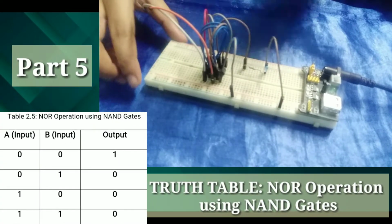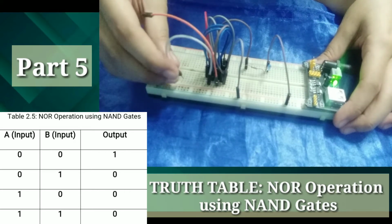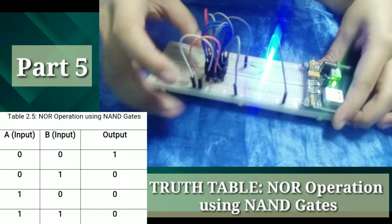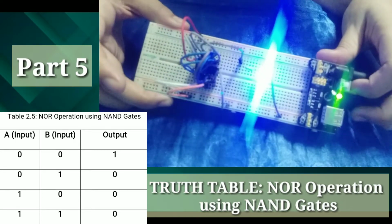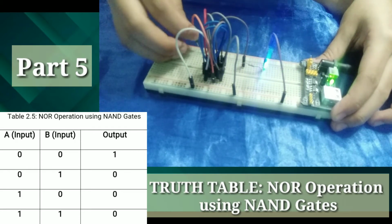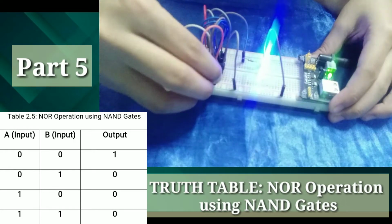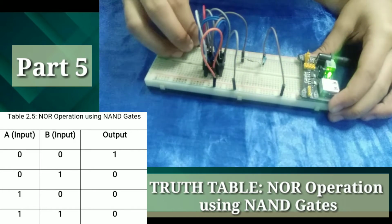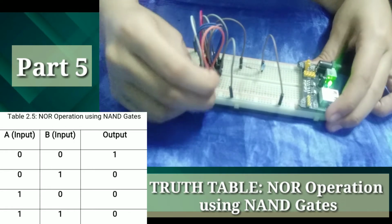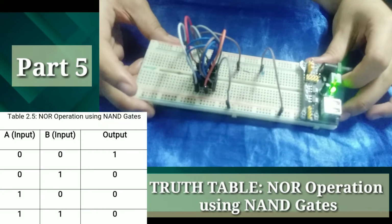Now, for part 5's truth table, let's turn on the voltage supply. So, if both of the inputs A and B are 0, okay, as you can see, the LED lights up. Then, if A is 0 and B is 1, the LED has been turned off. If we interchange the inputs, so A is now the one at 1, again, the LED is turned off. And lastly, if both inputs A and B are at 1, again, the LED is still off.